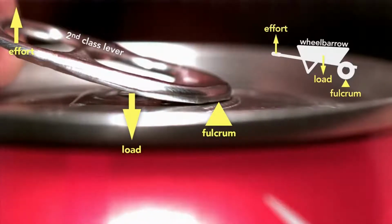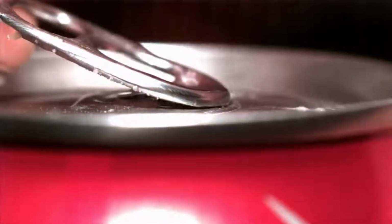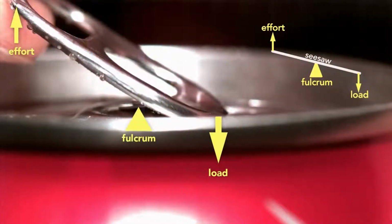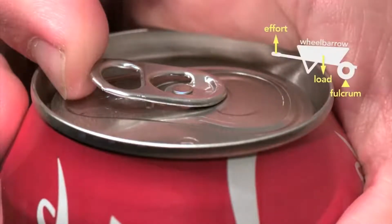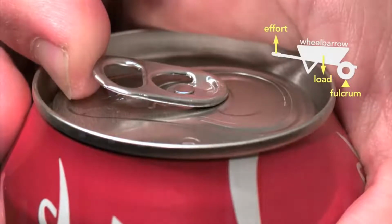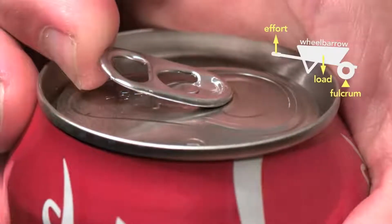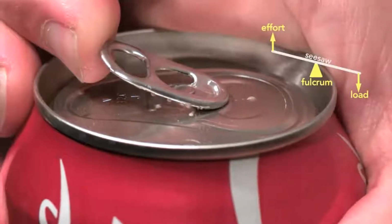But here's the genius part. The moment the can vents, the tab switches to a first-class lever, which is like a seesaw, where the load is now at the tip and the fulcrum is the rivet. You can see clearly how the tab, when working as a wheelbarrow, lifts the rivet. In fact, part of the reason this clever design works is because the pressure inside the can helps to force the rivet up, which in turn depresses the outer edge of the top until it vents the can, and then the tab changes to a seesaw lever.